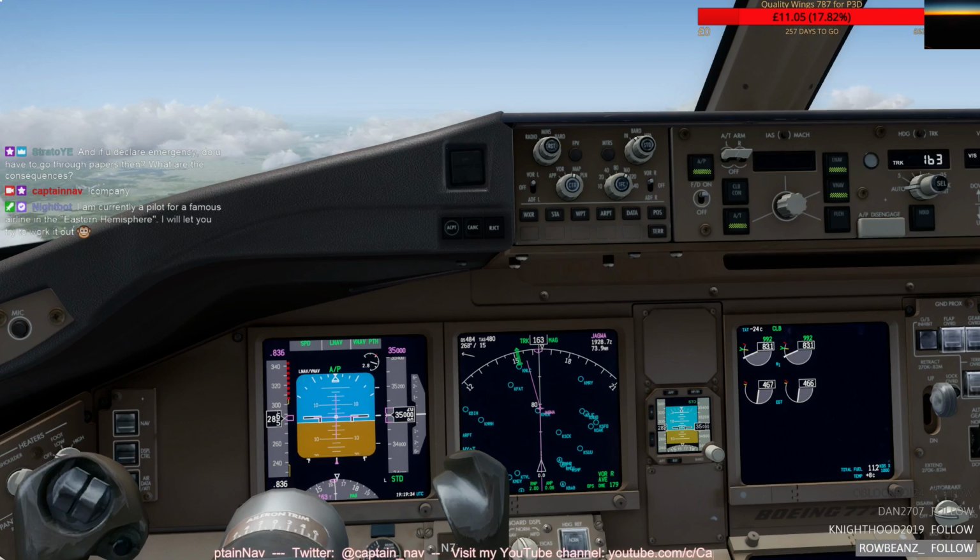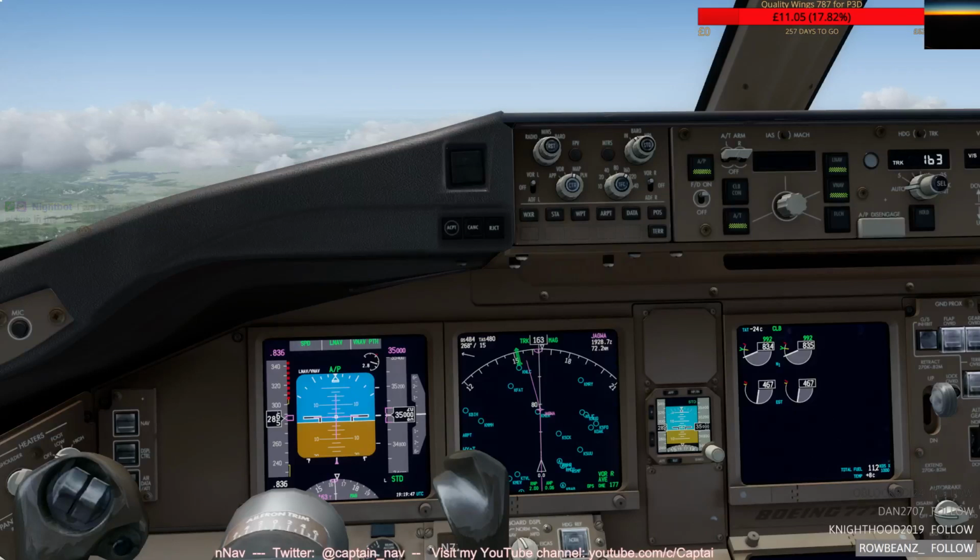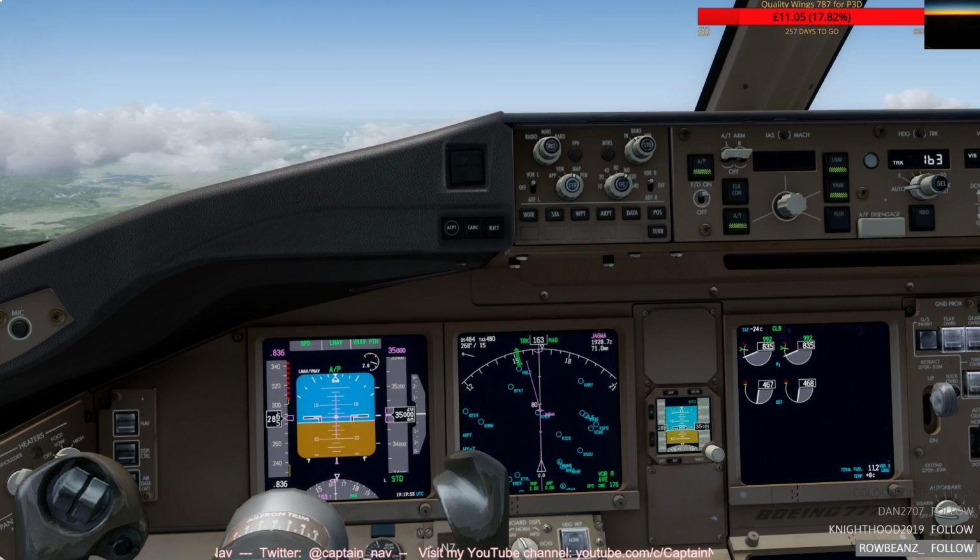Or for example, on a final approach, you say, okay, I'm landing, but if you make me go around, then I'm gonna be into a fuel emergency. So you're on final approach, and you say to air traffic control, okay, minimum fuel now, so don't make me go around, because if you make me go around, then I'm gonna be in a fuel emergency situation. So there's a couple of steps like this where you can preempt the situation a little bit, kind of say, hey, hold on, this is the situation now, don't mess around with me.